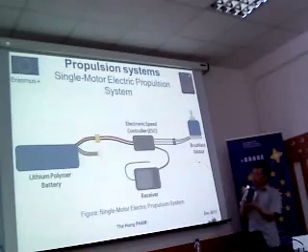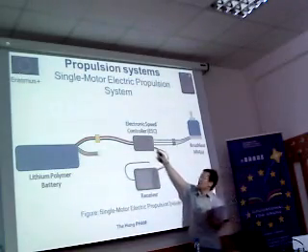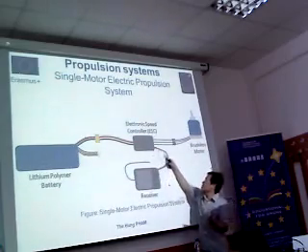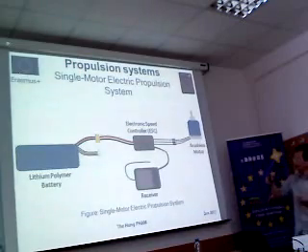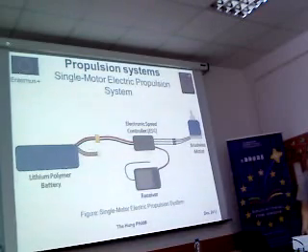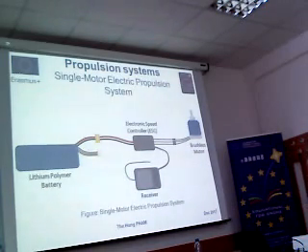So this one will send some signal to the receiver, and the receiver will send the signal to the ESC. This signal is exactly the PWM, and when we press some button on the joystick, the speed will be decreased or increased depending on the signal that we send to the receiver, and the receiver will send to the ESC. Okay.